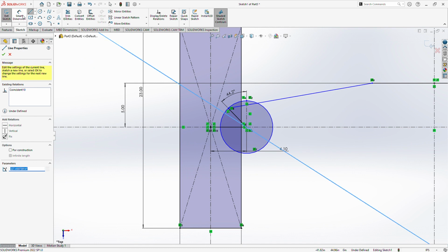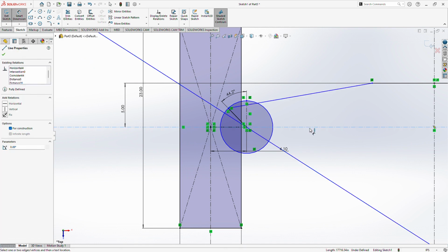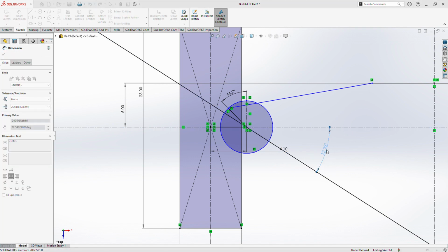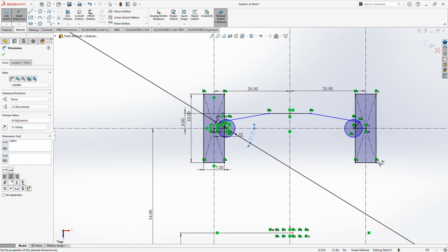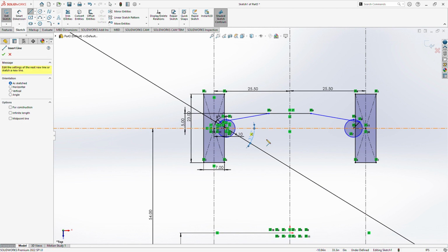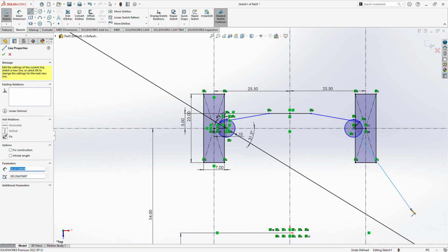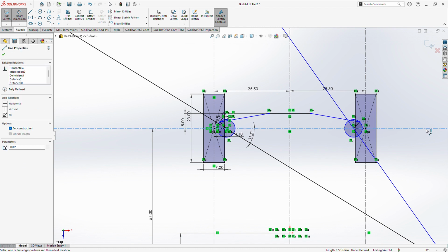Okay, assume the angle, this outer angle, 31.5 degrees. You have to make certain iterations to get the geometry perfectly right. Okay, when you put up the formula for the Ackermann, the 100% Ackermann will give the inner turning angle to be 49.99 degrees.